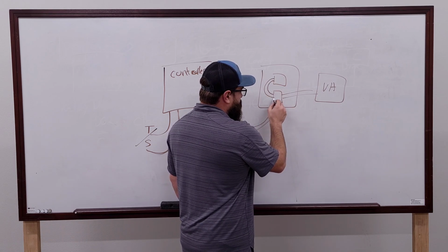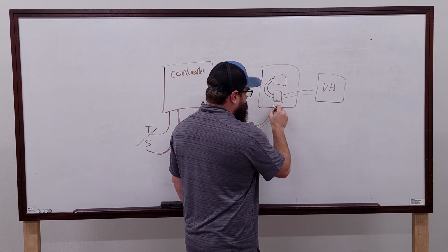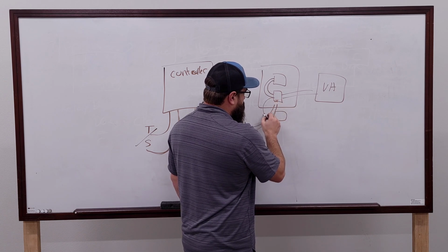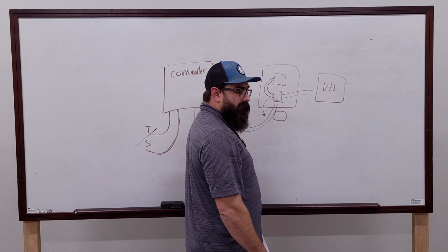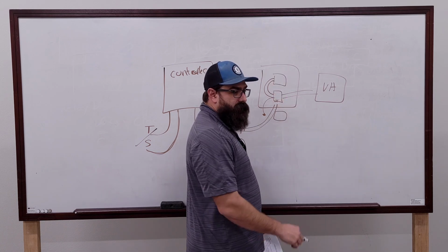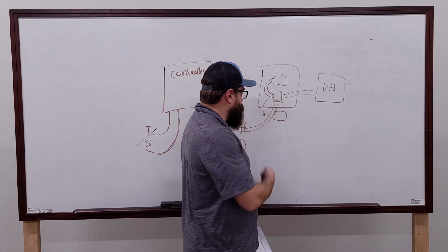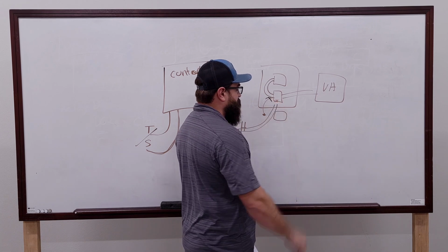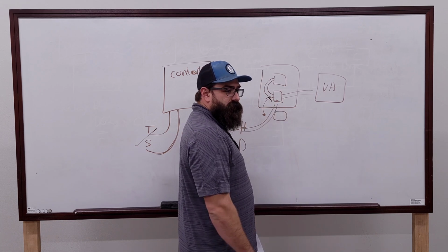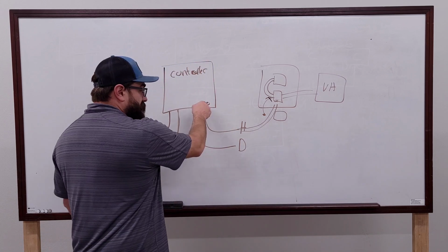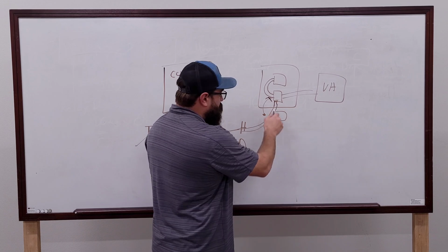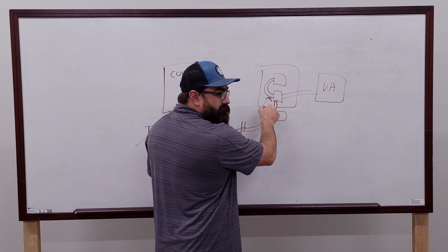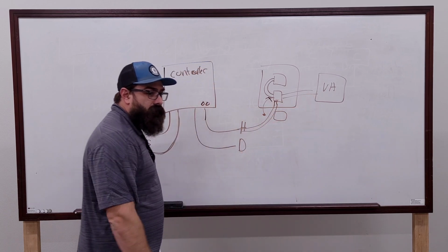Somebody had taken out the third EP in this panel and left this wire just hanging in the panel and it grounded itself out. And it shorted all of it and nothing was working because of a wire that nobody disconnected. So I had it here, I had it here, but if I would land this here, this was shorted internally to ground and I lost my signal.